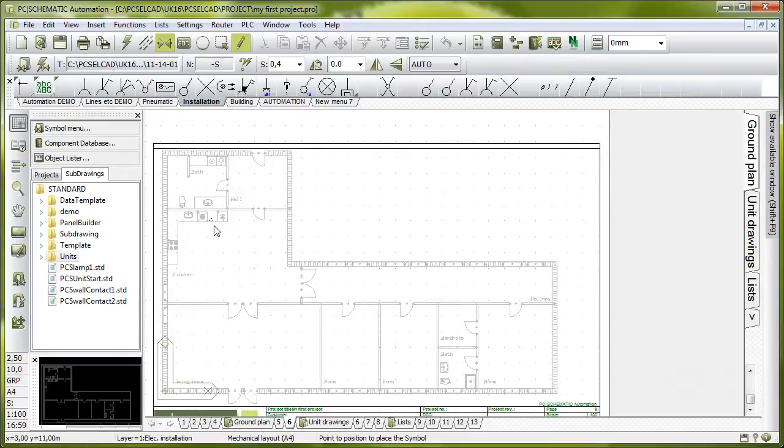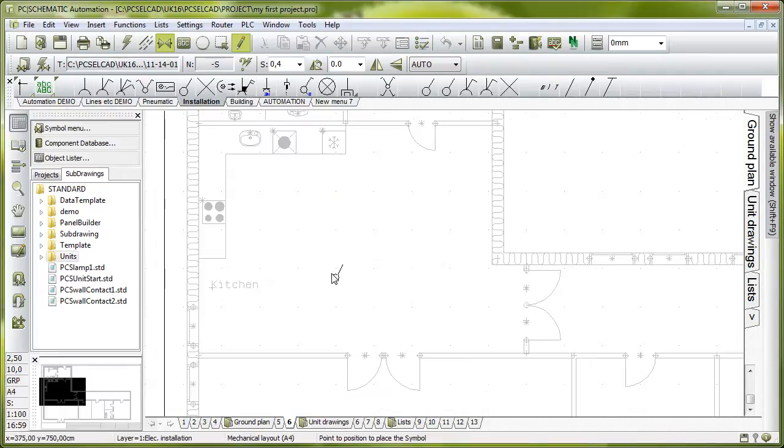But when I see a house plan, a floor plan like this one, I would also want to add information about where it sits. That means the elevation in which it sits. And look up here, I've got an elevation window. So if I want the switch to be placed not directly on the floor, but at 1 meter 10 maybe, I would go up here and simply type in the height that I want it to be.